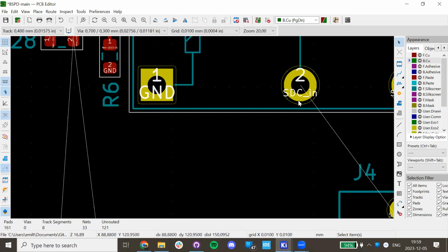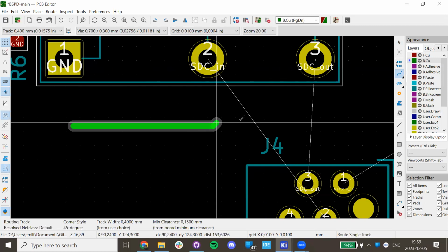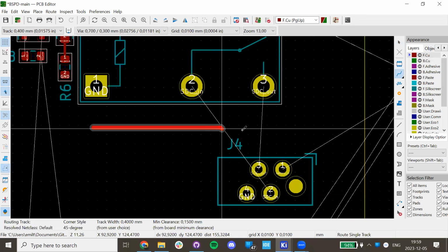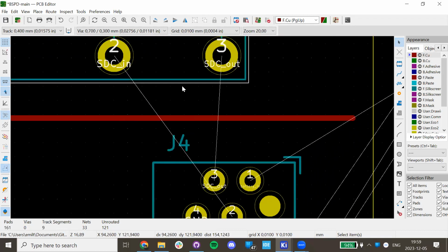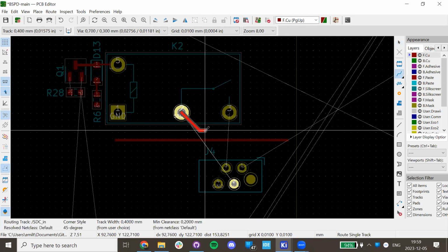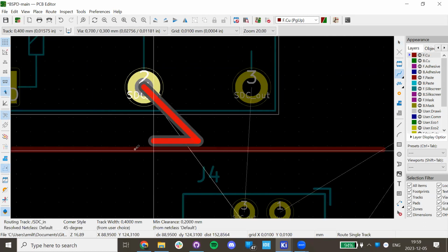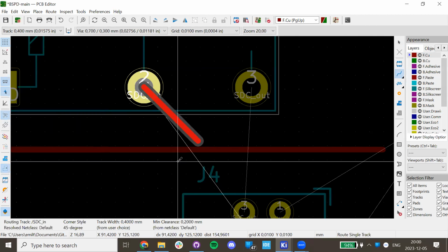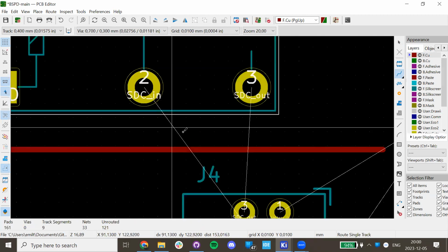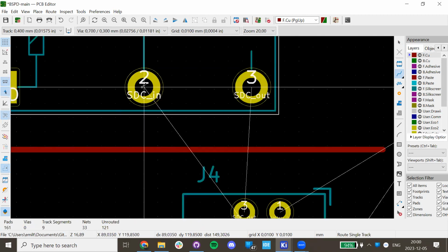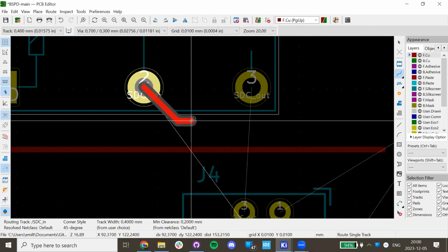So now let's just assume that there is, now I just have to pretend here a little bit. There is a trace running here, okay? This trace is between some components. And now I want to route this to shutdown circuit in. So I can't go around this trace, right? Okay, I can, but I can't go around it. So what are my possibilities? Well, here in this case, it's actually okay to route on the back plane.